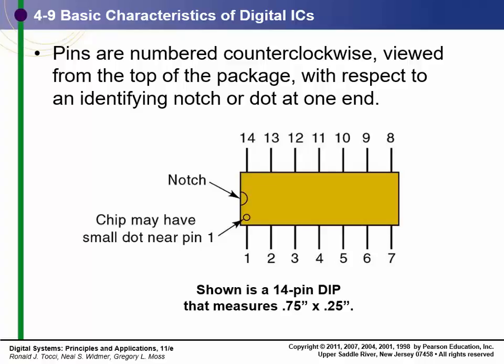As a matter of fact, I shouldn't use this red thing, as it doesn't show up in the recording. But in the bottom left-hand corner, your left-hand corner, you usually have a dot, or you'll have a notch. Some may have both, some have one or the other. That is pin 1, and they wrap around.